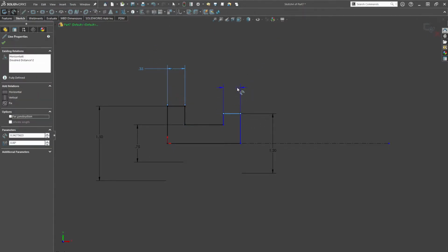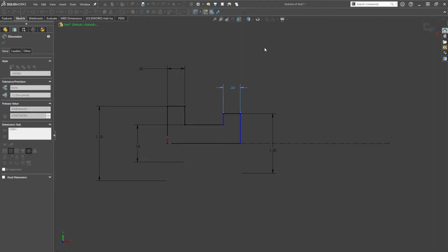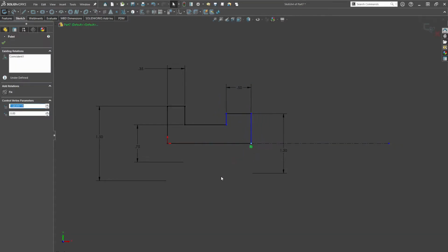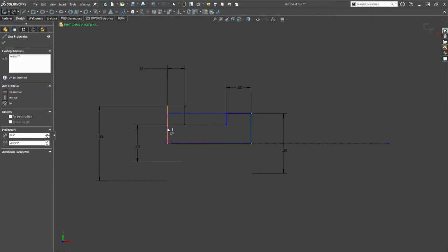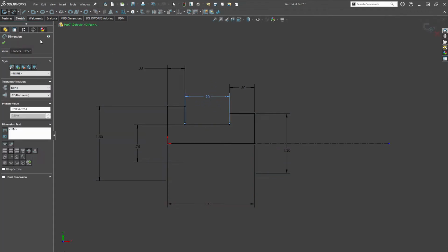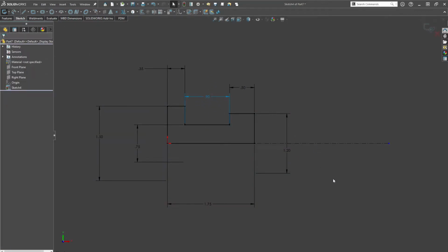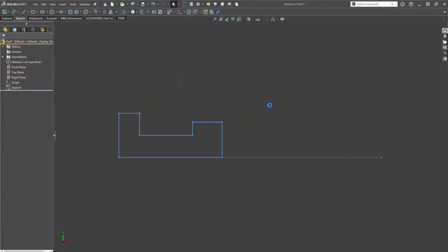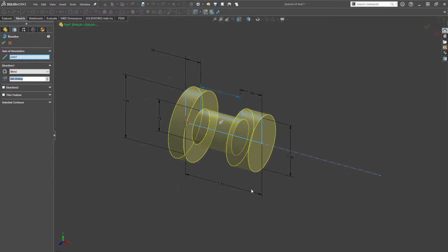So let's do this, and let's go ahead and make this guy 0.5. And, oh right, I need my overall height. And I say overall height, I could have also given it the height in between here. That is okay as well. I just chose to do overall height, even though in this case, the inside height probably did make more sense. So either way, now our sketch is fully defined. We have one center line here. So when I close this, it will automatically choose to revolve it.